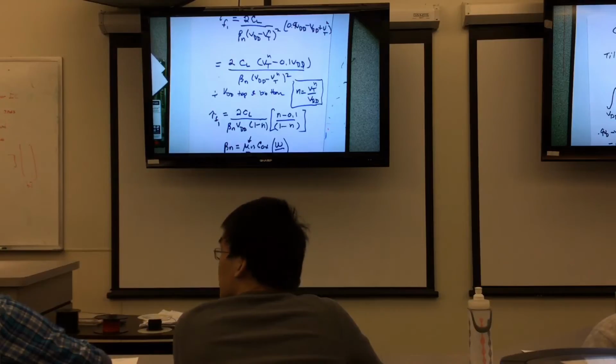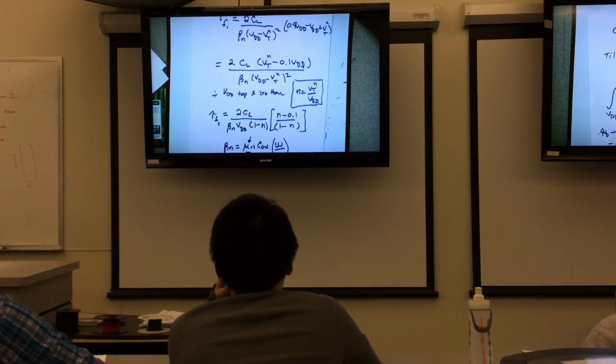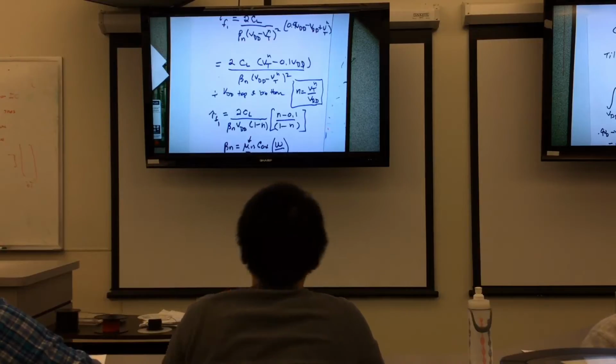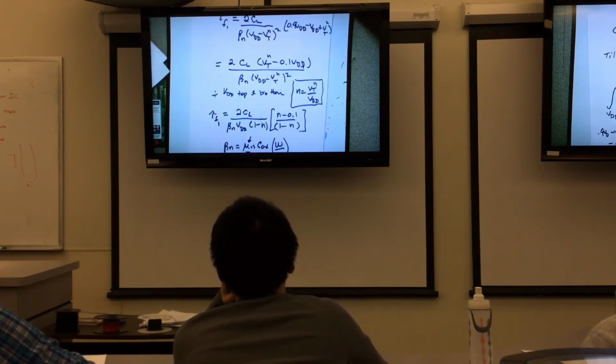You can find lots of things that have dielectric constants normalized to epsilon naught of 20 or 30. Trouble is, you could make a thicker oxide then, so maybe you could avoid some yield issues. Trouble is, it's not very uniform. It's not like silicon dioxide. You have to make a wafer of 18 inches in diameter, absolute pristine oxide with a thin oxide.